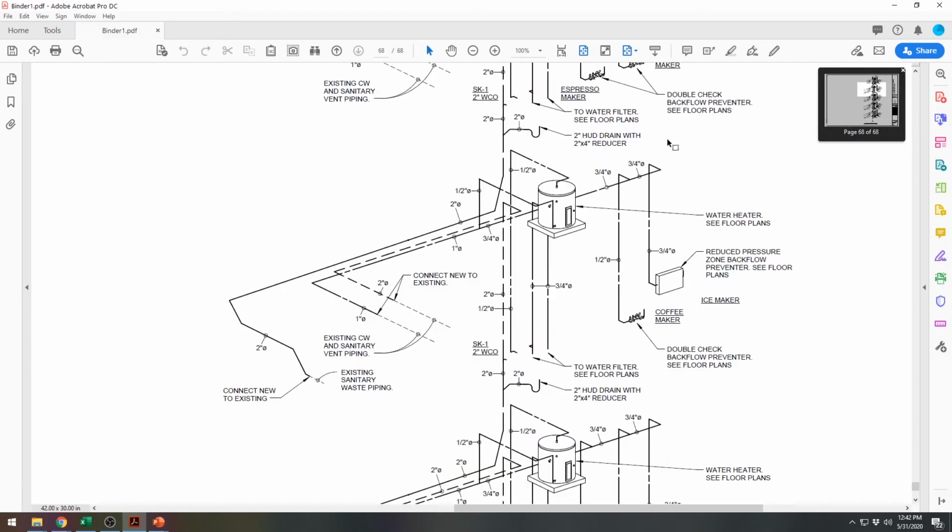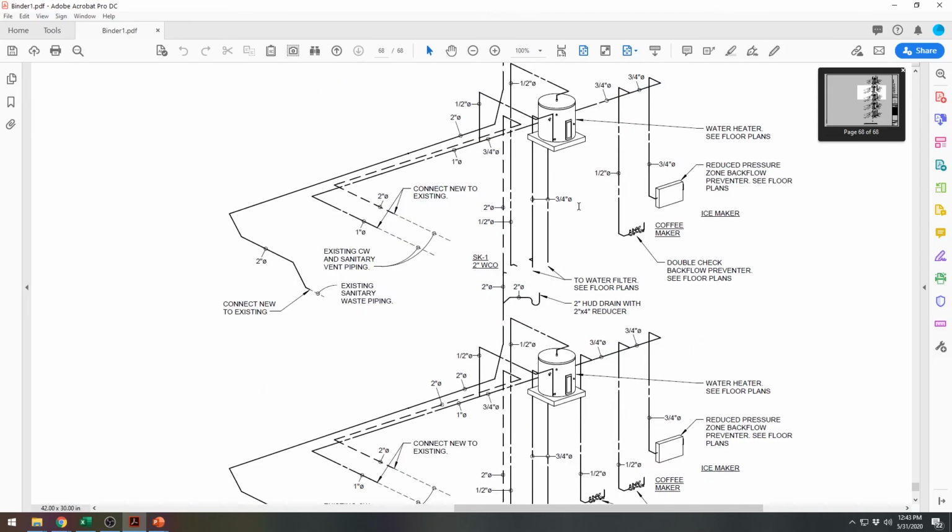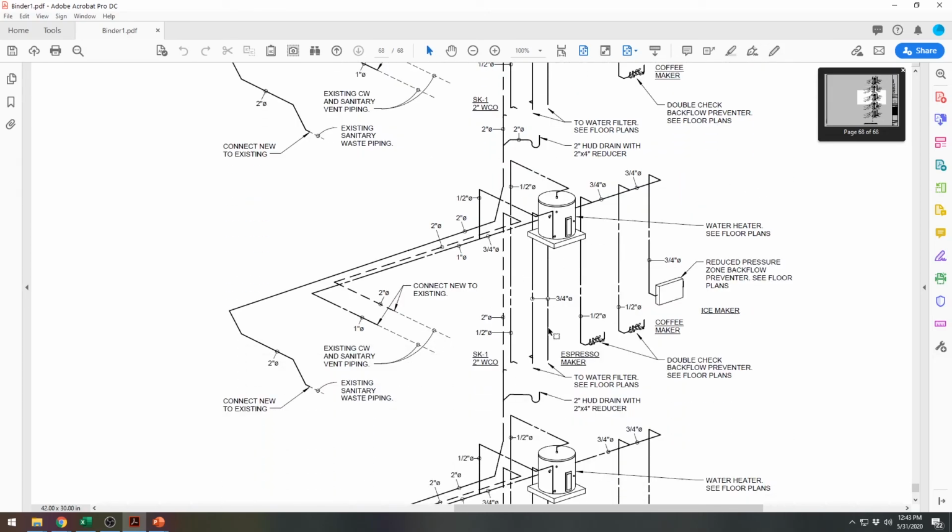This one was done in Revit, so it's a lot easier to build these riser diagrams, because you have your 3D space to actually create these pipes and run them in walls and overhead and underneath, and then you can just pull a view, remove everything except the pipe, and then set your visibility to look like this. Whereas in AutoCAD, the designers really have to think about what's overhead, what's underneath, and do a diagram. Versus Revit, you just draw it in 3D and set a view up. It basically makes it for you, and that's when you do your tags and your callouts for what's what.